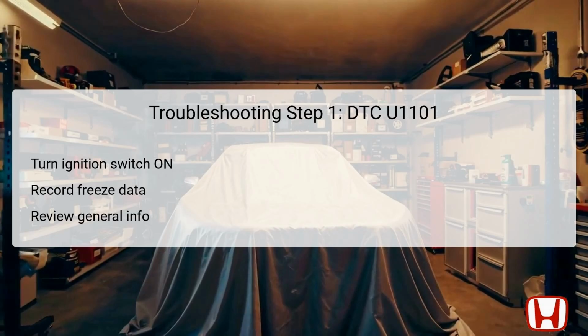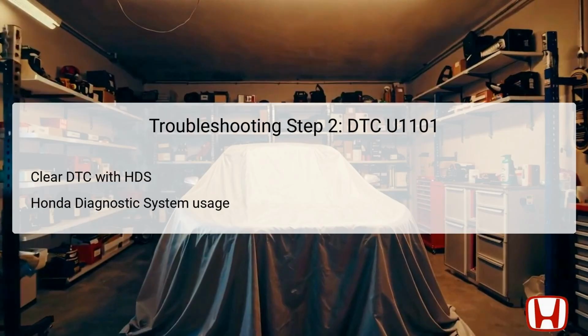Following this, it is imperative to review the general troubleshooting information for insights into specific diagnostic procedures associated with the DTC U1101. This foundational step ensures that all subsequent troubleshooting actions are based on solid data and context. In this step, the next logical action is to clear the diagnostic trouble code using the Honda Diagnostic System, HDS.